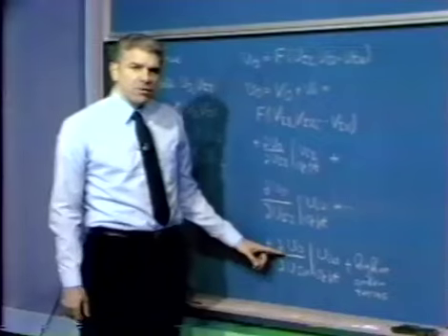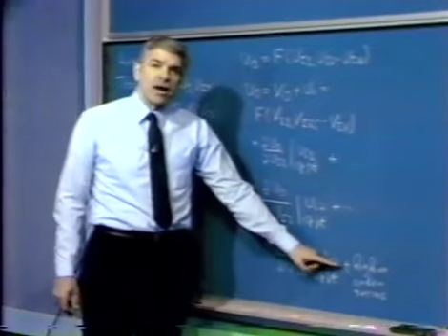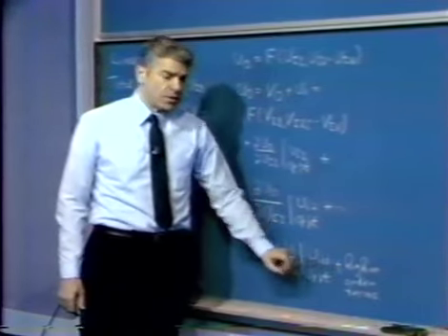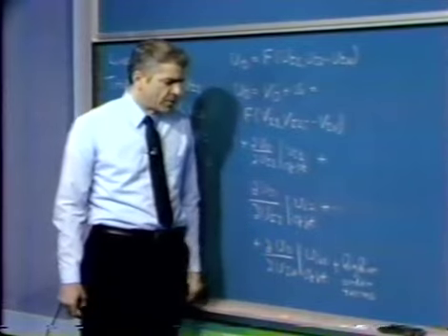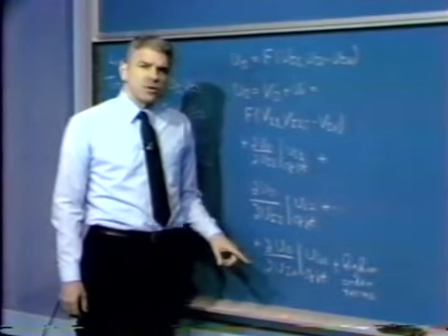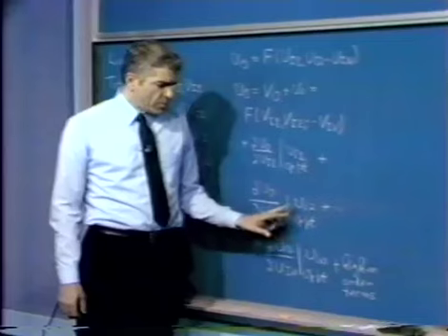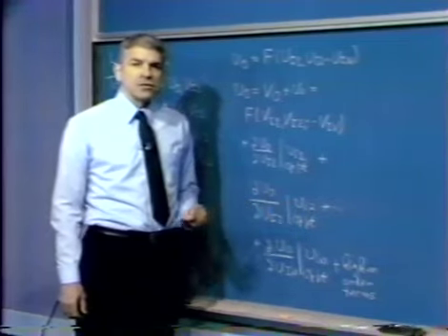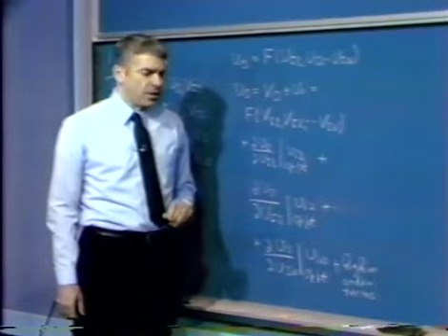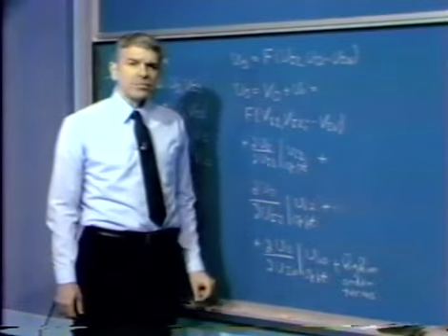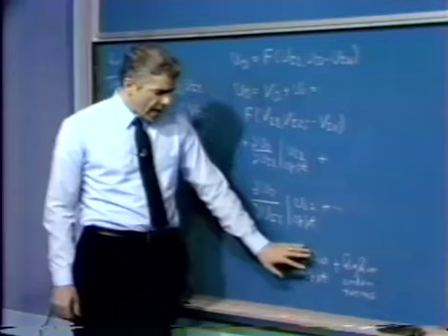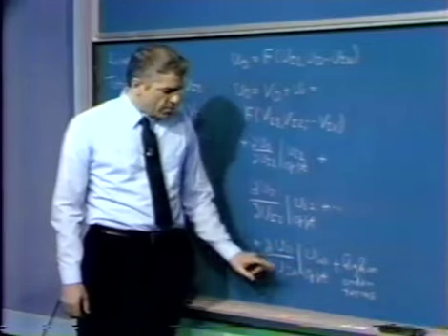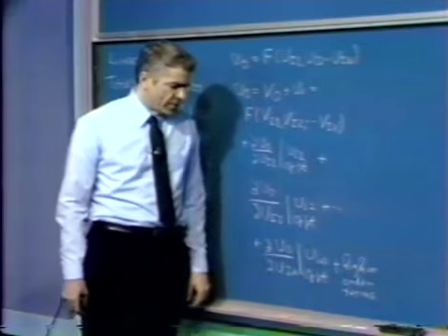And now if we continued a Taylor series expansion, there'd be higher order terms associated with this collection. But all of those higher order terms would involve products of incremental variables, such that we had at least the square of an incremental variable, or the product of one incremental variable times another one, as the quantity multiplying our coefficient.